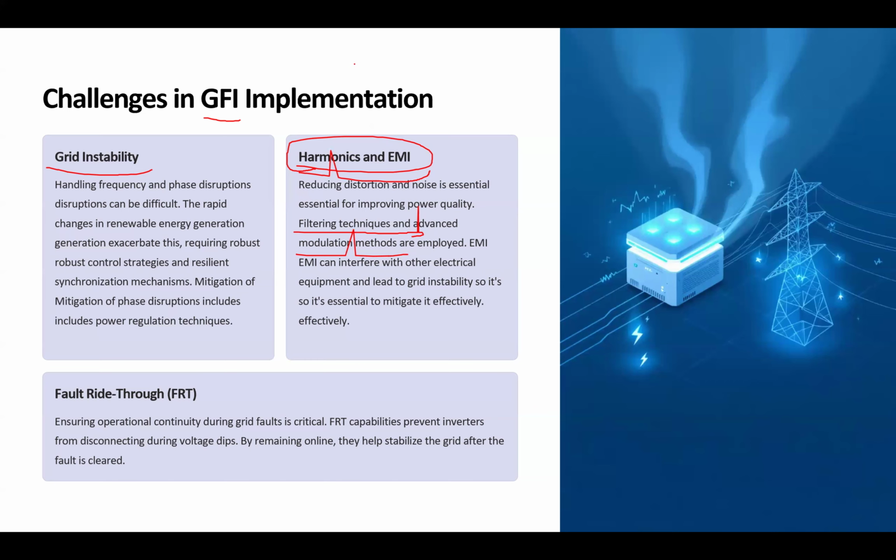Now we said that in our block diagram of the grid following, beside the switches and the filters and the synchronization that we talked about with the PLL, we need a control system that controls the active power, reactive power, and current control as a secondary control. Normally the basic control system that you could imagine to use as your strategy is a simple PID feedback loop.